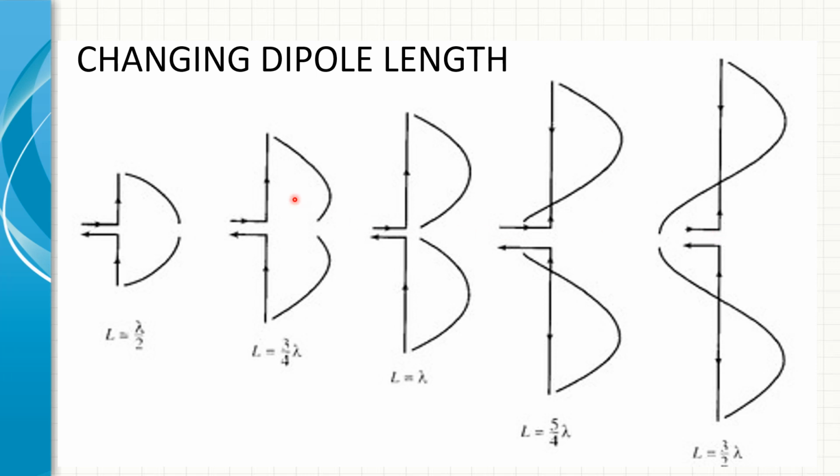And this relates to, you may have heard that an antenna that'll operate on 40 meters, when operating on 15 meters, fed at the same center point by 50 ohm coax, will also work, because you've got three lobes, which means 3 times the frequency. So there's a little trick for you.